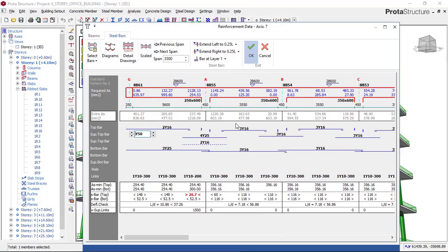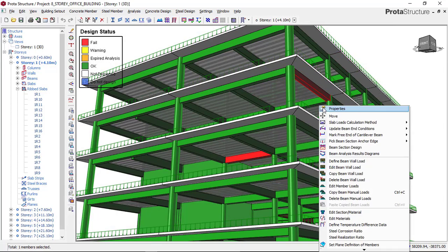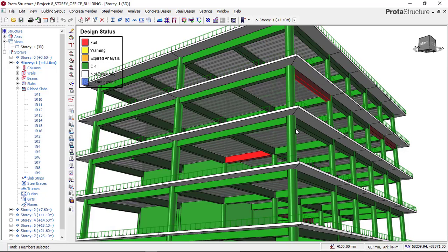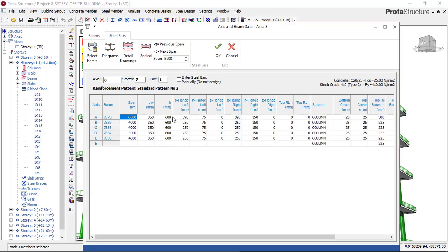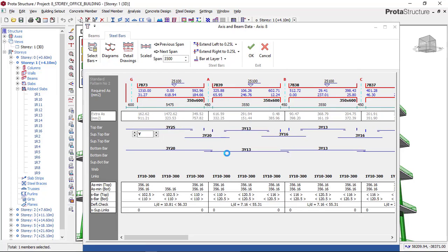So right now again, I go to check the next one showing red. Okay, this is now okay. So let us check on this one here. You can see that this is showing red. It's trying to hide, but no way, we are seeing that right now. So you must check your beams one after the other, because if you miss anything here, that member will fail, and when that member fails, it might cause the collapse of the building.